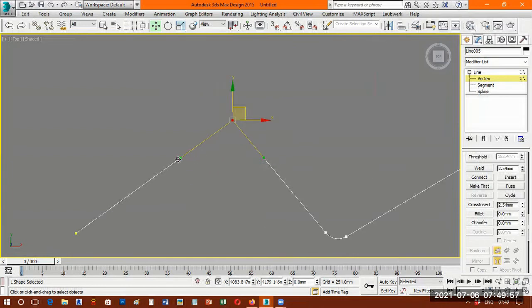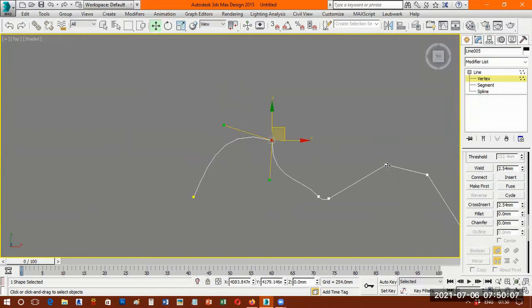If I take a Bezier corner, you can see some green color handles here as well. These 2 points here, I can transfer like this. I can take out this bulge. I can twist or tilt the line edges like this. I repeat again. Select any one of the edge here.